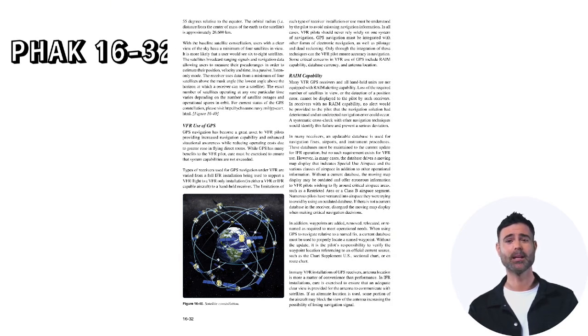Without a current database, the moving map display may be outdated and offer erroneous information to VFR pilots wishing to fly around critical airspace areas, such as a restricted area or a Class B airspace segment. Numerous pilots have ventured into airspace they were trying to avoid by using an outdated database. If there is not a current database in the receiver, disregard the moving map display when making critical navigation decisions.